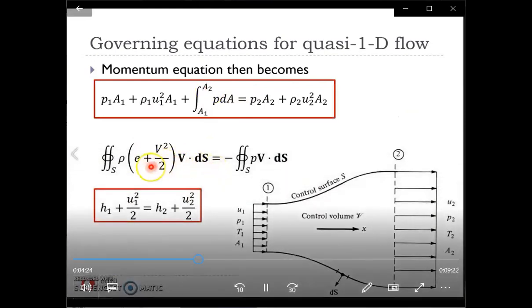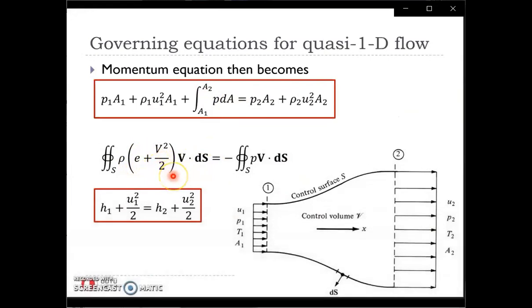If you write the energy equation, it has to be energy conservation, meaning the incoming internal plus kinetic energy has to be conserved. If there is an energy imbalance when we compare the exit to the inlet, that has to be balanced by pressure work.